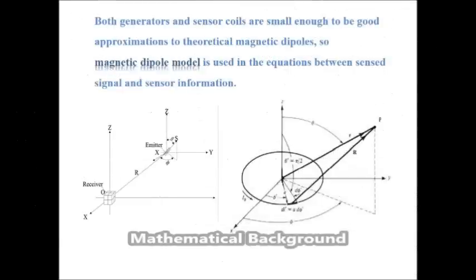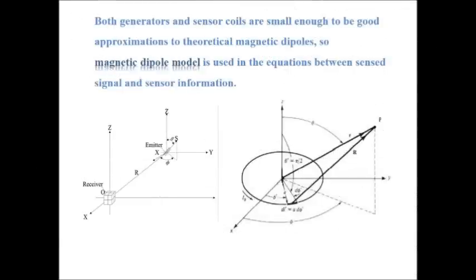The fundamental principle of the electromagnetic method for localization is that the electromagnetic signal caused by driving electrical coils with sine signals has a specific spatial feature. The receiver with 3 axes of coils that are pointed to the x-axis, y-axis, and z-axis respectively is located at the origin. Emitter P is a coil with axis pointed to vector S. R is the distance between the receiver and the emitter.